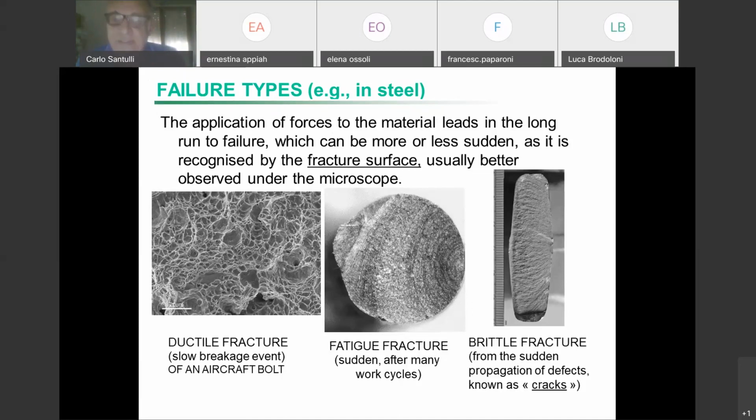To give you an example, which we will talk about later on, the studies on glass fatigue fracture started from the sinking of the Titanic in 1912. The reason for the sinking was the explosion of the ship windows, because they were loaded by the pressure of water a high number of times, even if in a few minutes or so.